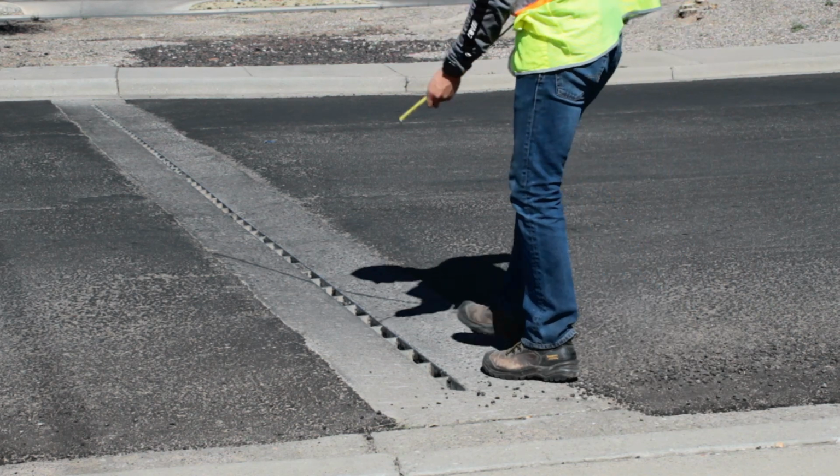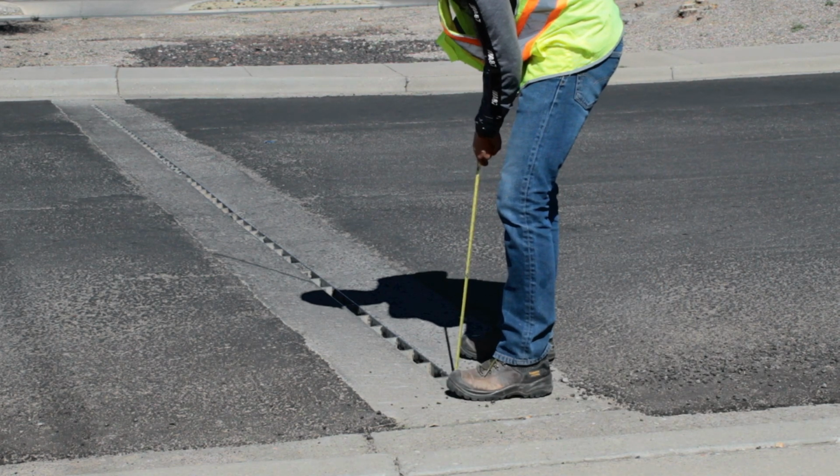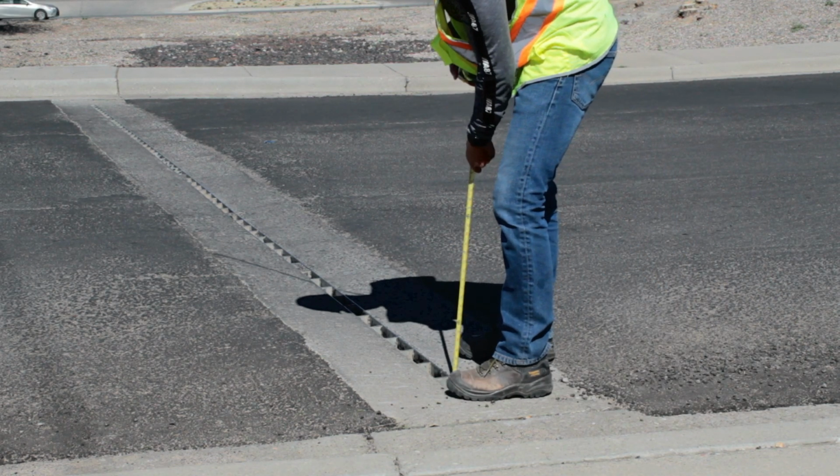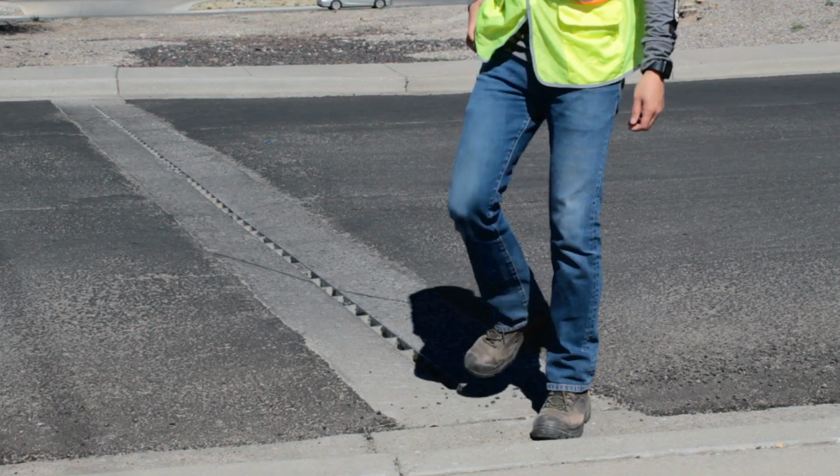Slot drains are metal culverts with a narrow grate placed above, usually along a highway curb. The pipe associated comes in 18 or 24 inches diameter. Try to measure by placing the tape measure in the slot and put the value into rise.